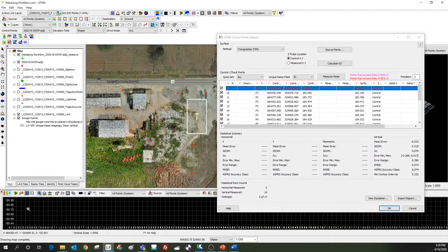And so with that in mind, this project that I'm reviewing in this example, this is a site we fly all the time. So I've marked my control points and checkpoints accordingly, and even the points that either fall outside of my project area or they're in grassy areas, I've marked accordingly as well. So the points I'm going to be using I've marked as FC for full check.